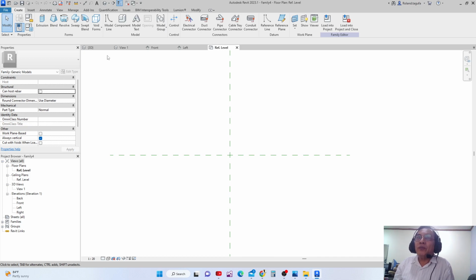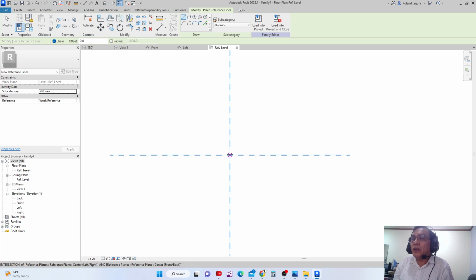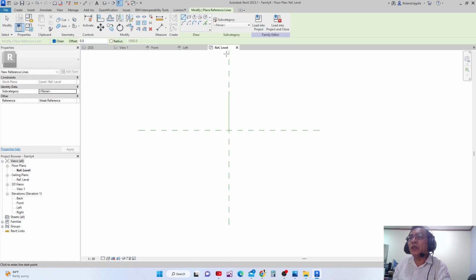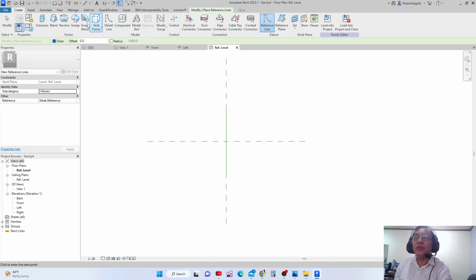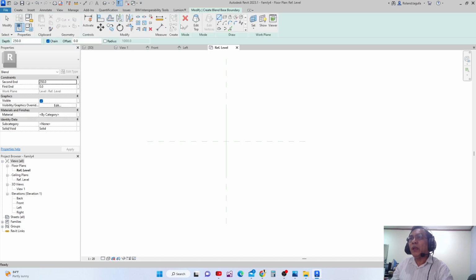First, I'm going to make a reference line, and I reference it here, and here. And then another reference line that I'm going to make is going here to here, any point. And then next I'm going to go to blend, and in blend I just wanted to set a plane.